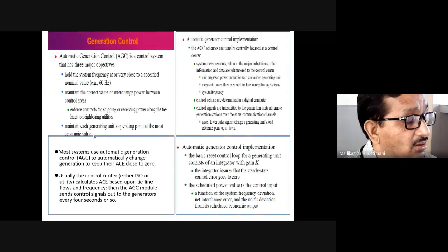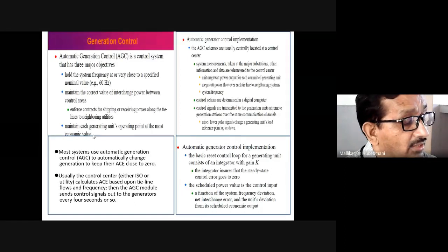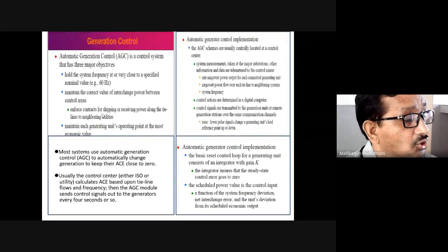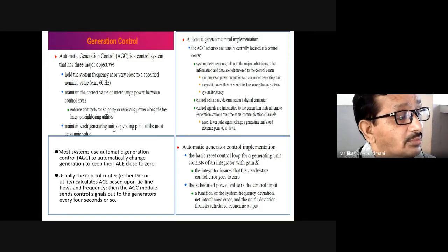A variety of generations are interconnected: hydro, thermal, oil or gas fired, or renewable, etc. Those generations depend on their fuel cost functions, cost of production, and incremental fuel cost of each unit. According to that, and the changes that we find on the station, we call it a load duration curve. We should see to it that generation is adequate and able to meet that.